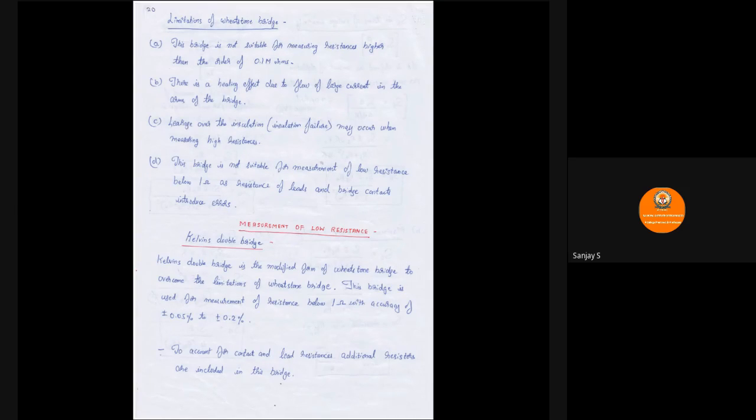So for now we'll have to talk about lead resistance and contact resistance. Lead is nothing but terminal of the component. Suppose you are having a resistor along with you. The resistor has two leads on either side for connecting purpose. It has two ends on either side. The two ends of the resistor basically are called leads. So those leads also contain some amount of minimum resistance, that is called lead resistance. Another one is contact resistance, where whenever you try to connect two resistances together, the point of contact wherever you are connecting also introduces some additional resistance.